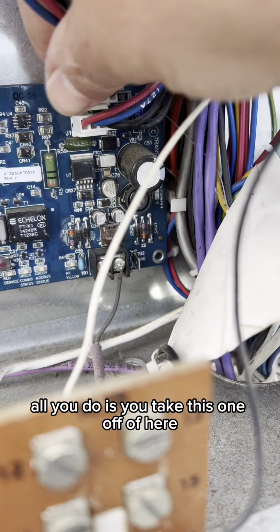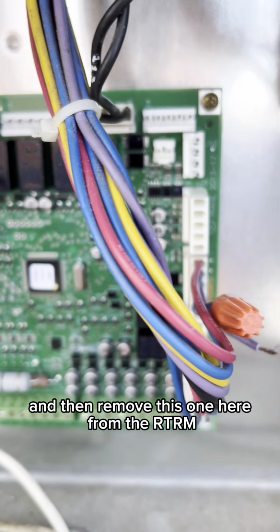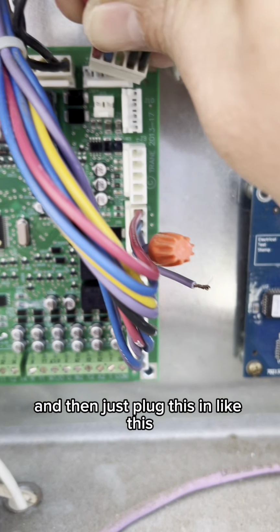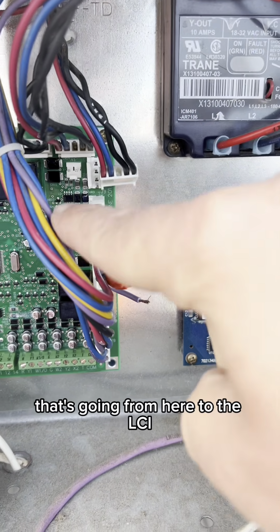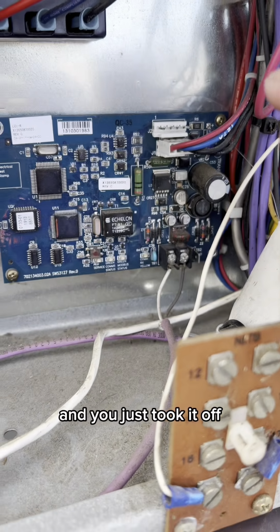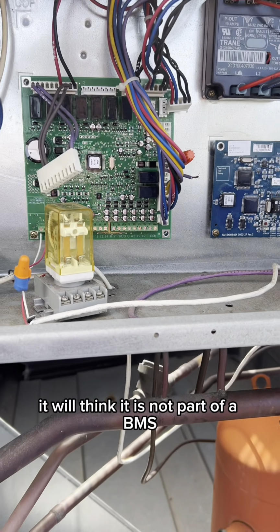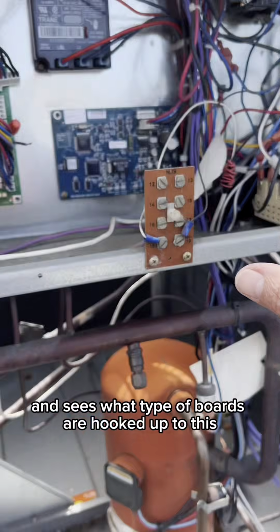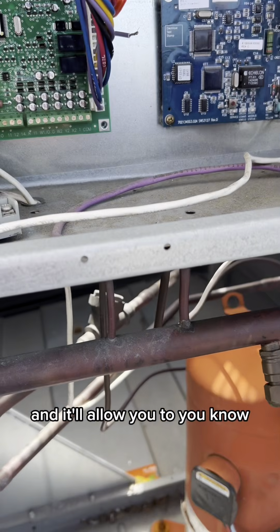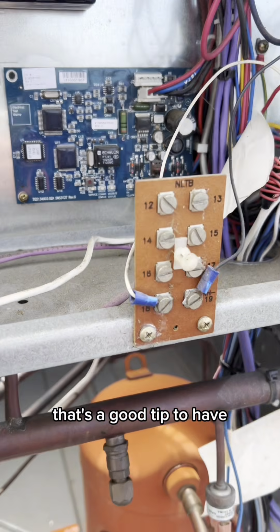All you do is you take this one off of here and then remove this one here from the RTRM and then just plug this in like this. Now what you just did is you took this jumper wire that's going from here to the LCI and took it off, and took the one that was on here and put it on here. So right now, when you power this unit back up, it will think it is not part of a BMS because, like I said, when the unit powers on, the RTRM does a who-is and sees what type of boards are hooked up to this. And it'll allow you to put it in test mode, run it through a thermostat, however you want to do it. That's a good tip to have because that happens sometimes.